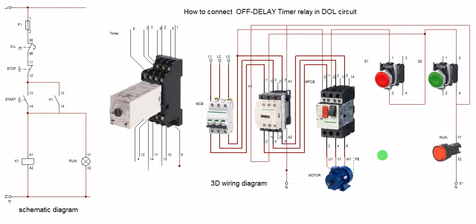It can be any equipment you want to operate within a range of period. So if you don't want to be present while the operation is going on, you want the system to shut down on completion of that particular task. You can use this relay, the off delay timer or the on delay timer, but the ideal relay suitable for that particular function is the off delay timer.